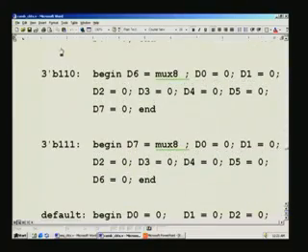And another point I may mention is that you have put everything in a sequential order, say a binary sequence, but there is no need for you to do that. Also, this may be painful to write with so many bits. If you have 64 inputs, you will have to write very many, and the larger the number, the more you have to write. So, a better thing would be to use decimal here. You can just replace this B with D, but even in that case this will mean only the number of bits. So, you have to take the trouble of first computing how many bits it will run into at maximum, then put this. So, this tick is a prerequisite here, and this colon is also a prerequisite here.